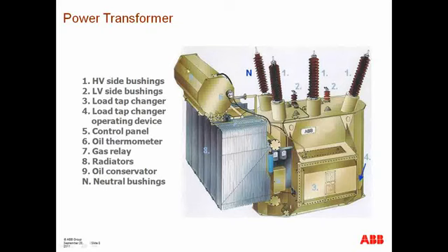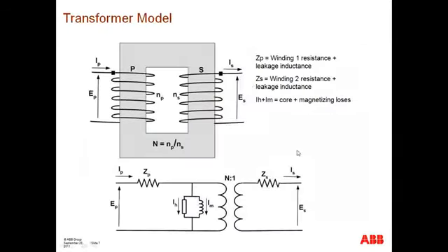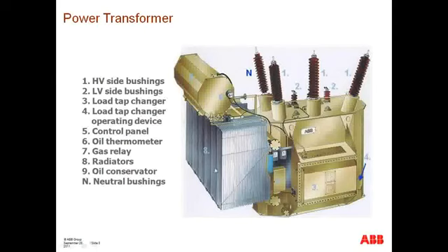Okay, and then number 9 here, this is something very important to recognize, and this is just an oil reservoir, where excess oil is stored. It's important to consider that most power transformers in operation are oil insulated. So I'm going to go back to this slide. You have your winding, you have your core, and that's inside this metal enclosure, okay? And that metal enclosure is filled with oil, and that oil is circulated and cooled via the radiator to maintain a normal operating temperature.